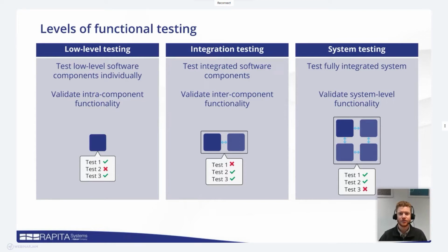And finally, you get to system level testing, where you really are testing the whole software or very large parts of the software in ways that are similar to how it's going to work in the field. Instead of at a low-level test or a software integration test where you might be introducing data into some subsystem, during system testing you are usually using the software's external interface and driving it as it would be in an aircraft or other vehicle.